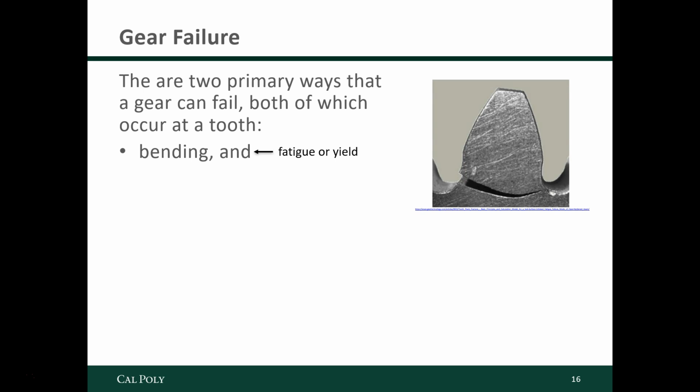And so that can also cause compressive stresses, so cycles of compressive and tensile stress, and that can make fatigue even worse. And so that means that it could fracture at a load that's lower than the load at which you'd normally expect it to fail. It's maybe even lower than yield, but certainly lower than the ultimate tensile strength of the material.